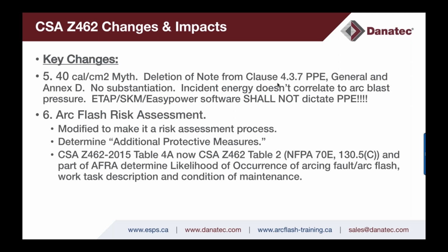So this is going to further exacerbate the issue for a host employer or a company that owns the power distribution equipment. There's an ongoing effort to get this 40 cal number removed from industry, so that in your risk assessment procedure you're going to use PPE up to 140 calories. I'm glad to talk about that offline. If you want to email me, we can have a conversation and I can follow up and give you more information on that.